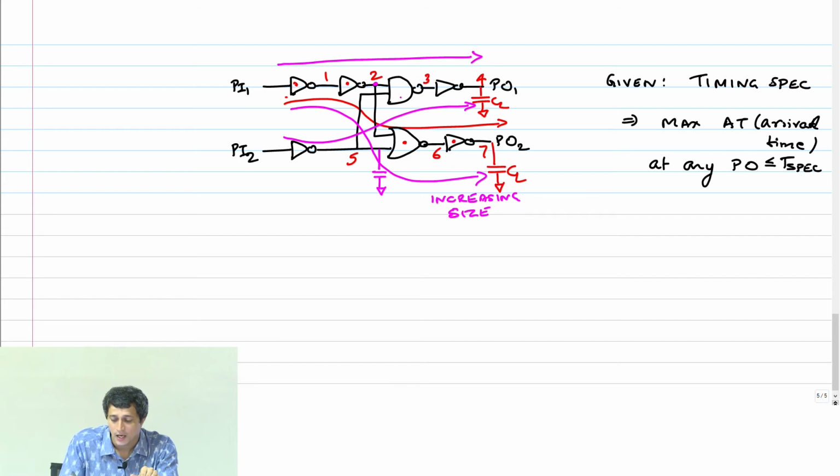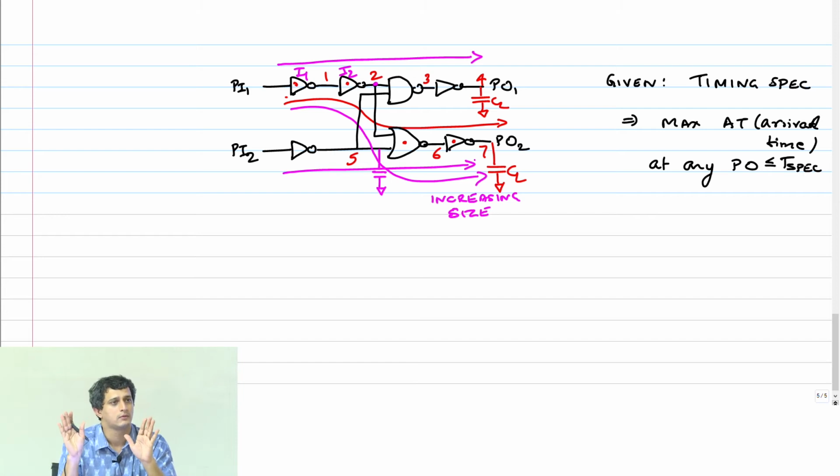Because that NAND gate, right? Wherever, no, not that path delay actually. This cannot go up. It is only the other path delay that can go up, right? Whichever is connected to that inverter I1, I2. Since the NOR is connected to I2, that delay can go up. Similarly, this delay can go up, right?